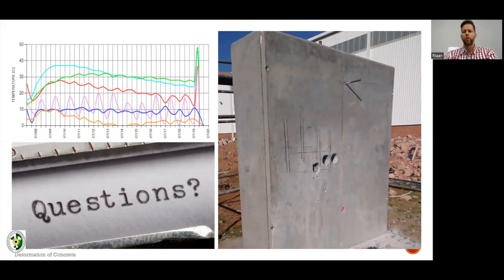and you were to take one of those 19 millimeter stones, and you were able to break it in half, what happens to the surface area of those two halves of a 19 millimeter? You end up with two extra surface areas to that aggregate. It's like breaking a muffin in half. You end up with more surface area. So if you have concrete, your cement and your hydration products have to coat everything in your concrete. It does coat everything. That solution of water and cement particles covers everything. So the more surface area you have, the more paste you have.